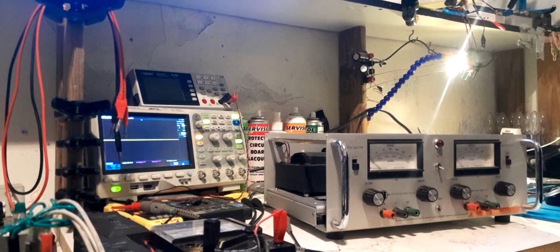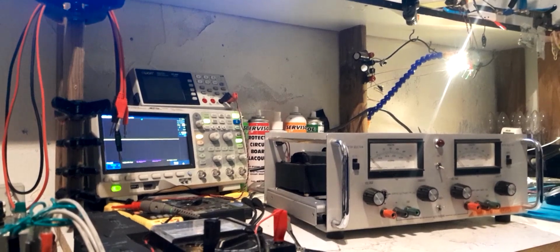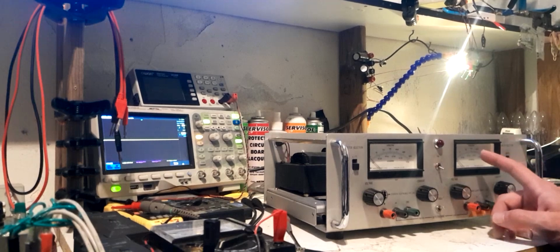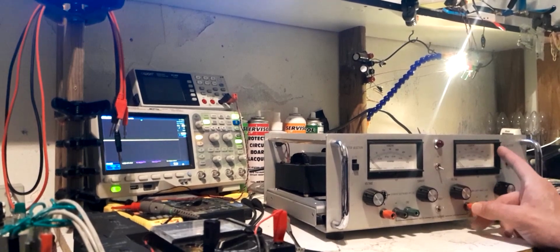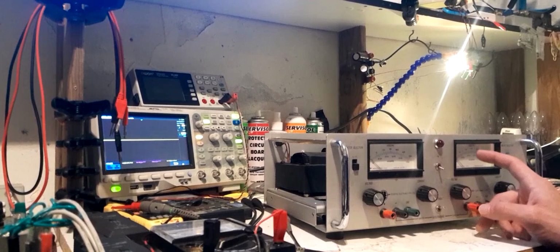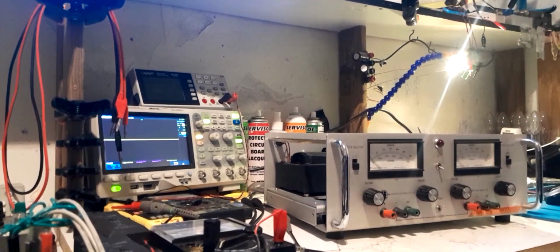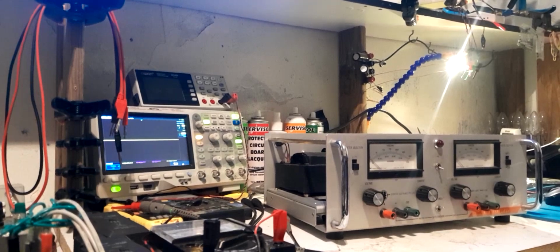But if you wanted a quick demo, I could put a ridiculously big cap on there, and you'd see when I turn it on, the voltage would go up way higher and then come down as the cap charges up and the reference voltage comes back up, and that would be a problem. So we can only add so much capacitance to the reference, which is why I might end up using the other reference, because it might be easier to compensate with less capacitance.